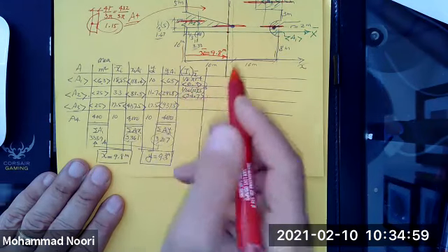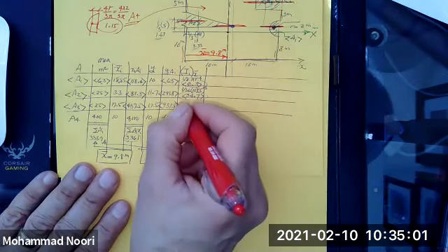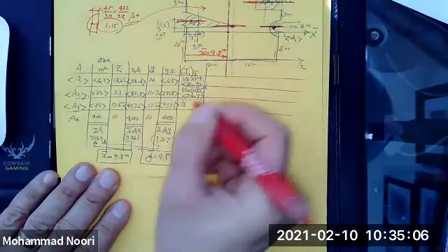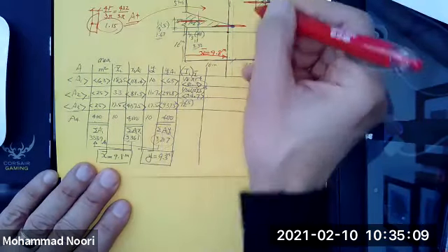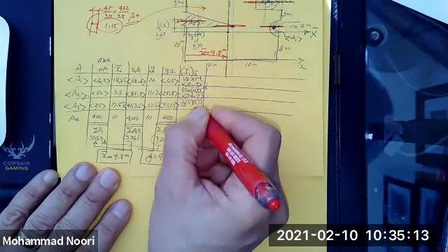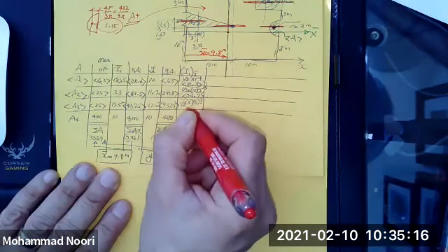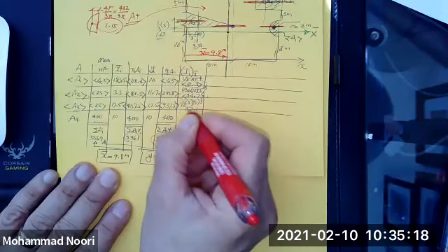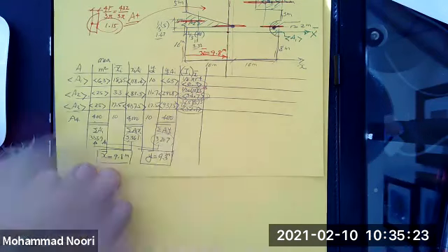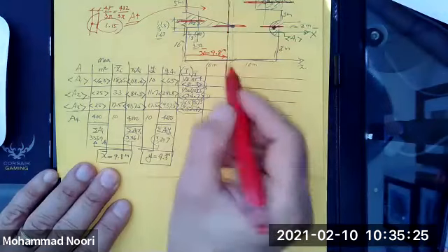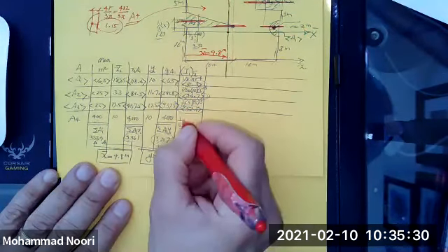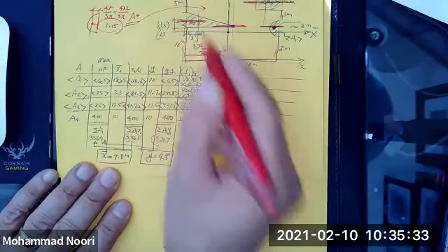For this one it's 1/12 of the base, which is 5, times height cubed, which is also 5. You evaluate that, you get 52.1, which is also negative. And for this one it's 1/12 of base 20 times height cubed.